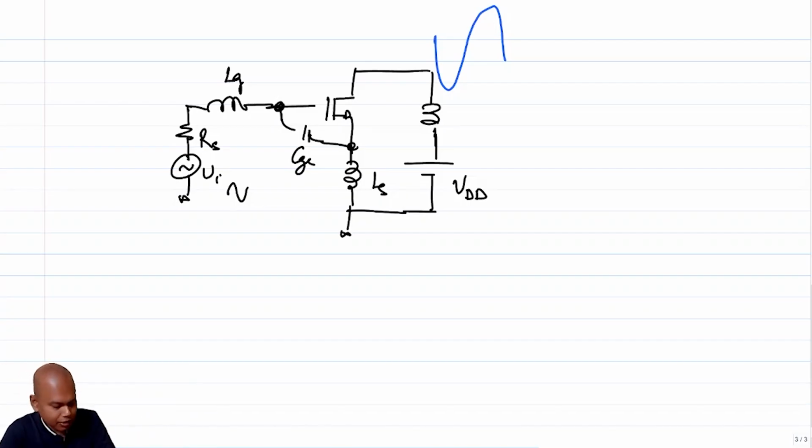But the problem that will appear is, and I will not prove this, but intuitively you can understand that just like this CGS capacitance is creating a real part of the impedance, similarly the CGD capacitance, which is between the gate and the drain, will also create some real part of the impedance and effectively affect the input match.